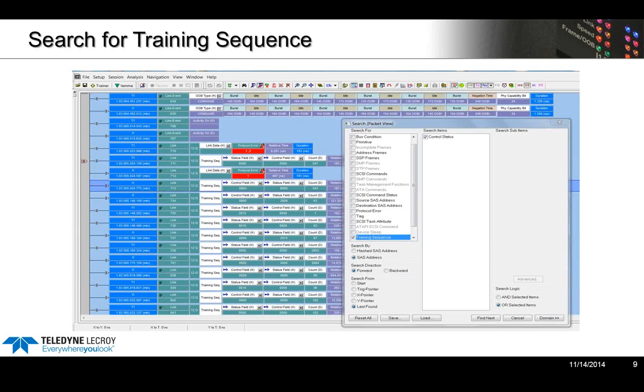So in this slide here, at the top, we can see the end of the PHY capability bits exchange, and then we launch into our first 12G training receiver and transmitter training sequence. You might note there that the analyzer decodes the PHY capabilities bits exchange as COM-wake, because that's what it looks like to the analyzer.